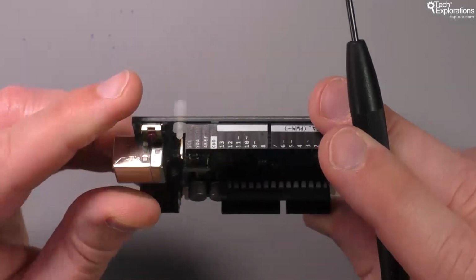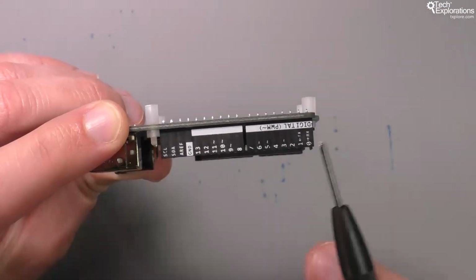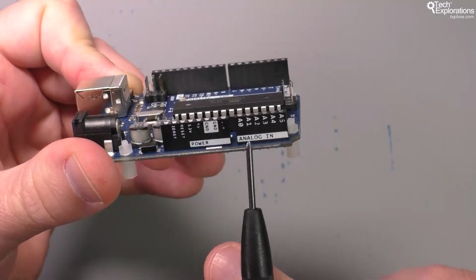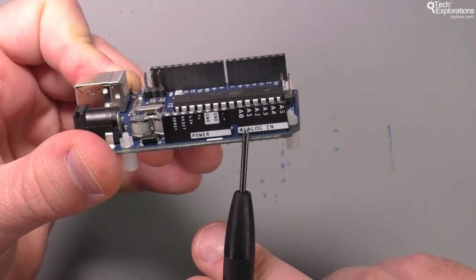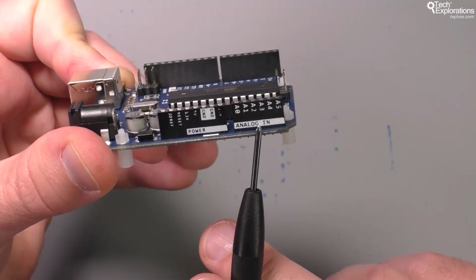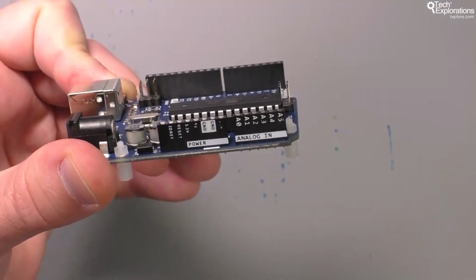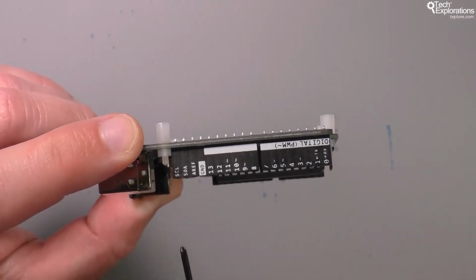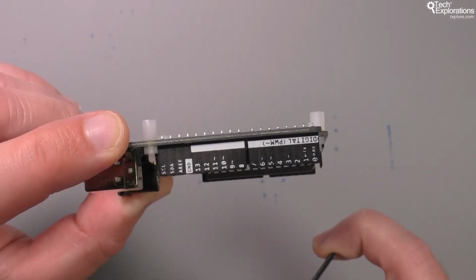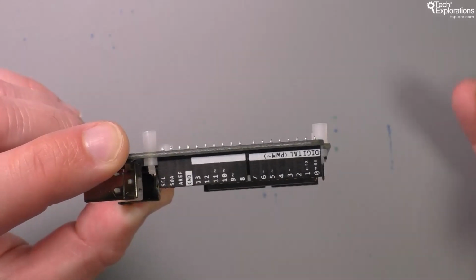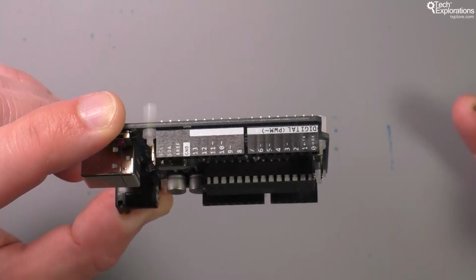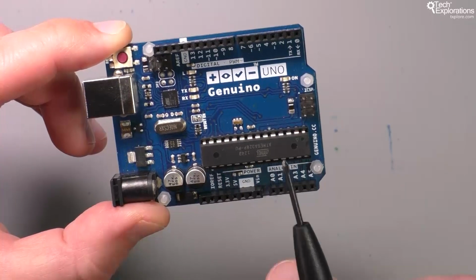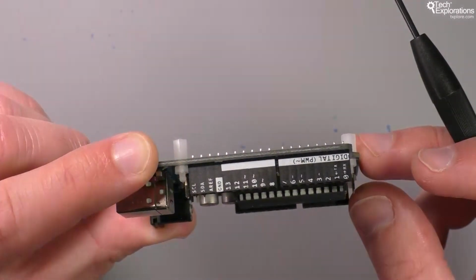Now, what do these markings mean? What could these two pins here and another two pins here do? On the other side, we don't really have any other clues other than the functionality of the analog pins as analog pins. So we know that there's something going on here. Well, these 4 pins can be used for communications, and they implement 2 of the available 3 types of serial communication protocols that the Arduino Uno with its Atmega 328P microcontroller makes available to us.